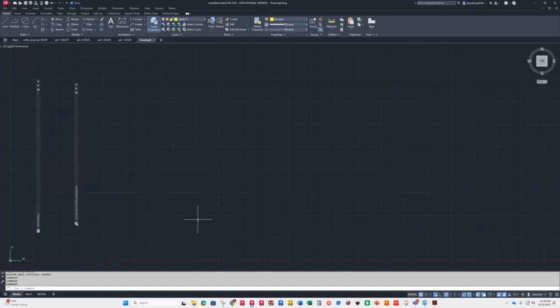And you'll notice that on the original drawing you're given here, this isometric, that it has a bunch of lines on it, vertical lines. Those are for shading. They basically took a 3D drawing and it does that with shading. We don't show that, okay? So there's no extra lines.